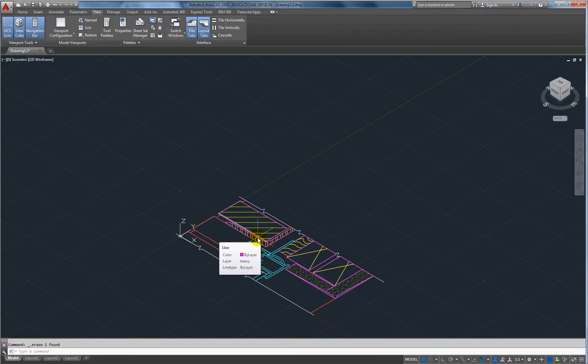Why is that important? Eventually, when we start adding things like materials, we want to make sure the right side is facing outward, and we're seeing the right side, right? Similar to the way we load paper in our printer, and we want to make sure it prints on a specific side, we want to know which side is facing outward or directional, right? This becomes really important when it comes to materials. All right? And then solids defeat all of that because solids are fully capped. So that means they're watertight.